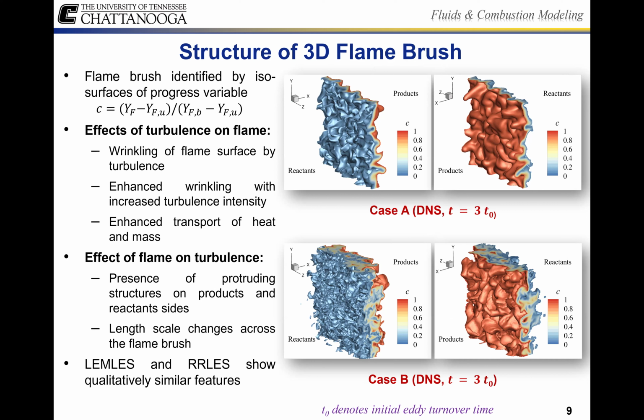A typical role of the turbulent eddy is to transport pockets of cold reactants toward the reaction zone, which sustains the flame. As expected, the flame structure is continuous, thus precluding any local extinction. The width of the flame brush varies spatially due to the straining effect of the large-scale eddies, and the increased flame surface area results in an increased fuel consumption rate.